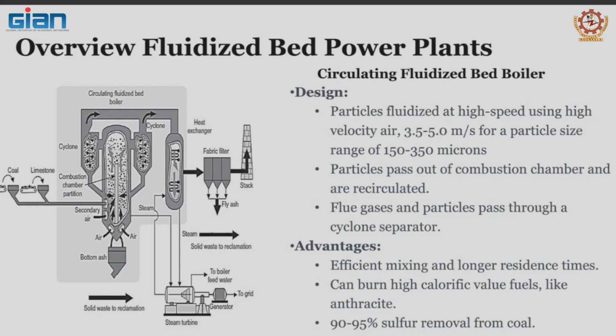With pulverized systems, because of the very high surface area ratio, you don't need to use a lot of excess air, because excess air, as the name implies, is just excess air. Even though it promotes complete combustion, it is lost through the stack, and it carries with it a lot of thermal mass.